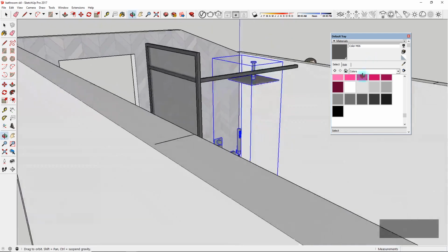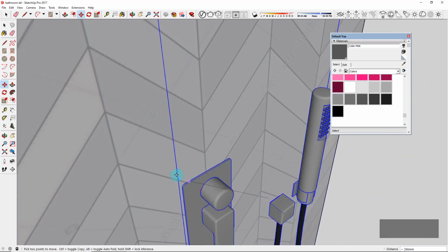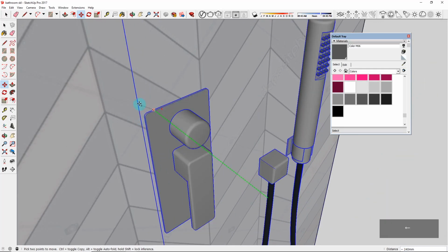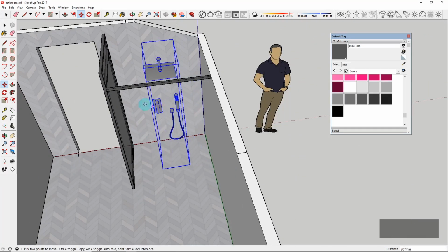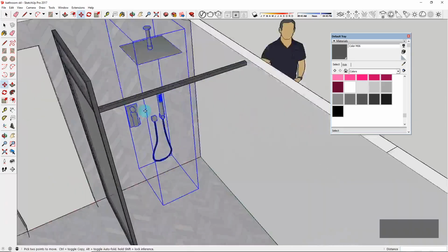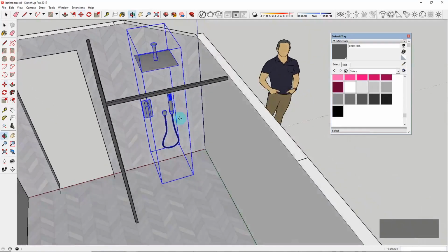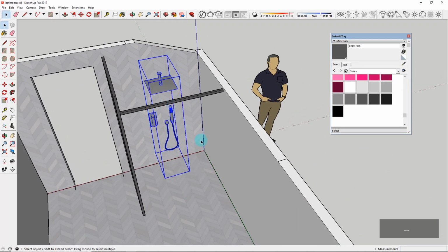And basically, I think we just want to keep the controls because these controls are quite nice. So I'm going to grab this edge and then put it onto our surface. And sometimes you've got to be careful when you import stuff. People build it on a massive scale, or sometimes on a tiny scale. But this one, that does look quite big for a handle, so I might just scale it down ever so slightly like that.